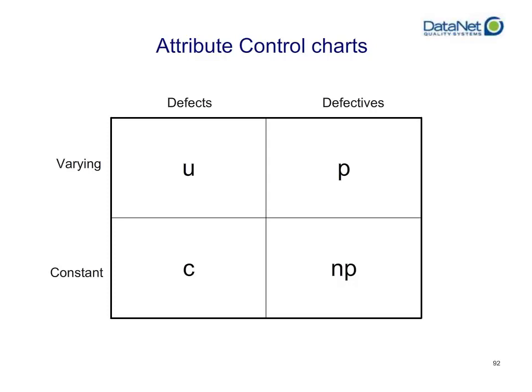Now, there are fundamental differences between counting defects and counting defective units, and therefore you have different control charts that present themselves. It's extremely important that you always pick a valid attribute chart type when you are doing attribute charts. Otherwise, you may come to incorrect, misleading, or blatantly incorrect conclusions if you pick the wrong chart type.